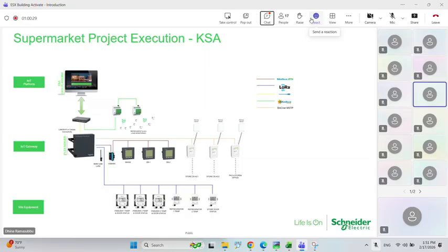We used Modbus RTU for metering, and BACnet MSTP for the SE8000 thermostats. Then we used Modbus TCP for PowerTag energy monitoring, and then there are LoRa sensors. All 4 communications went through Flux servers. Through that, we integrated around 20 equipments in this particular store. Additionally, we drove savings in the store, and we are expecting a potential scale-up to 30 more sites this year.